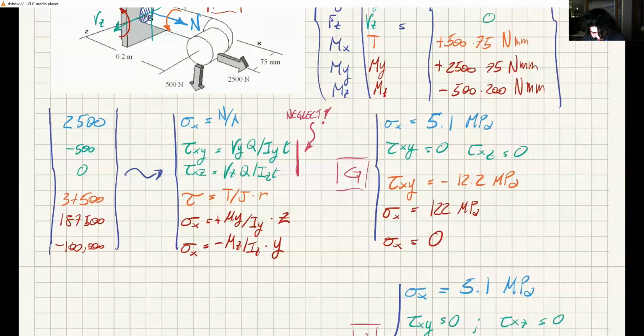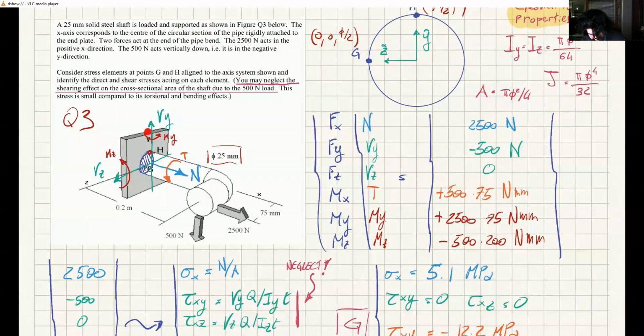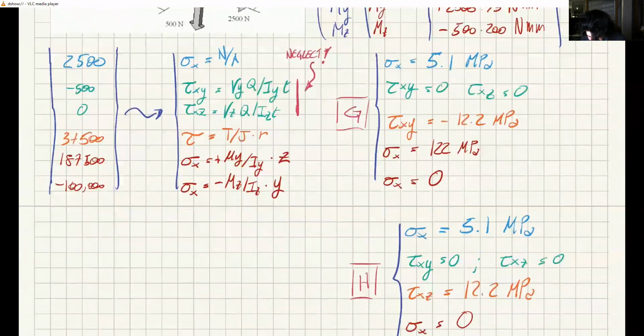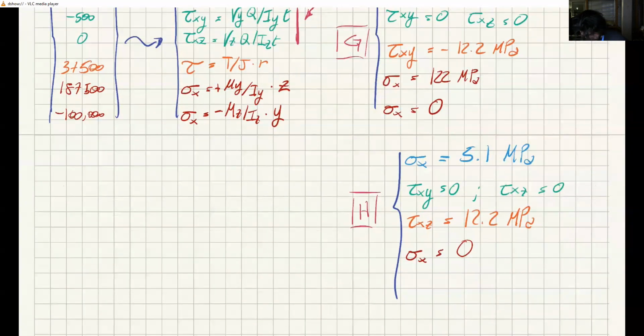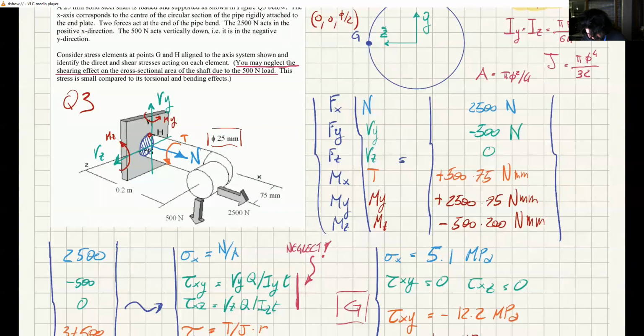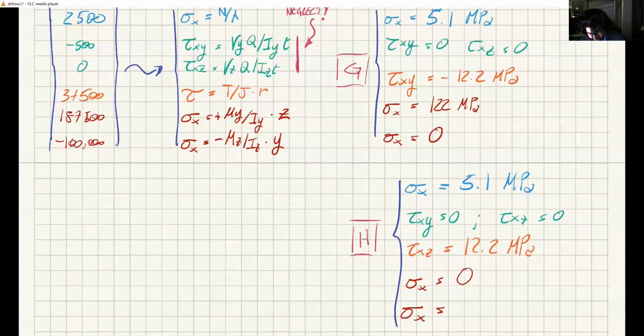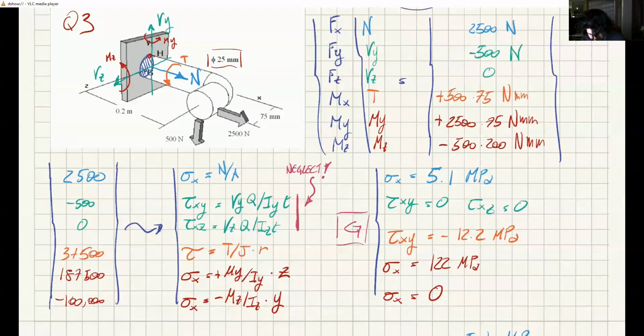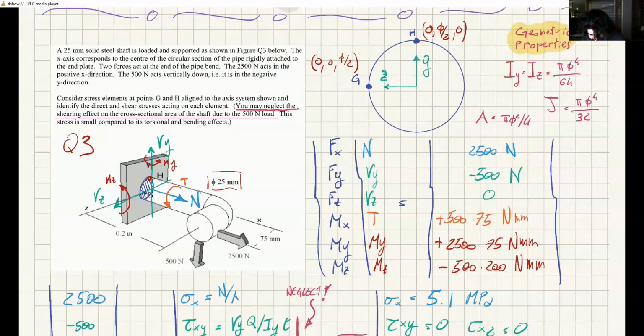We can test that because for this bending that we are considering, bending left and right, H is exactly on the neutral axis for this bending. So it doesn't feel the effect of that bending at all. But it does feel the tension from this bending down of the structure, which puts this top fiber in tension, by Mz.